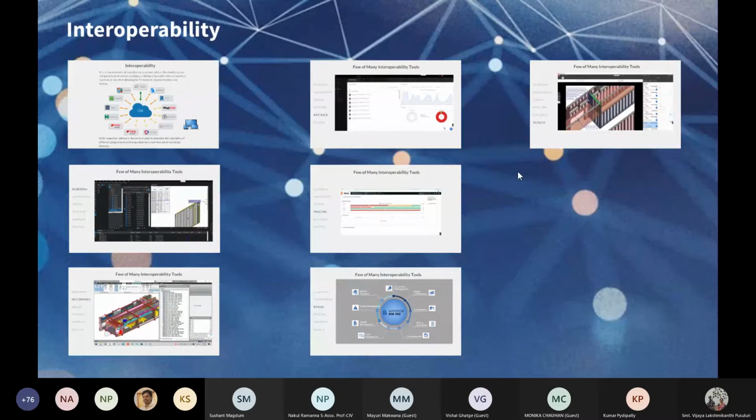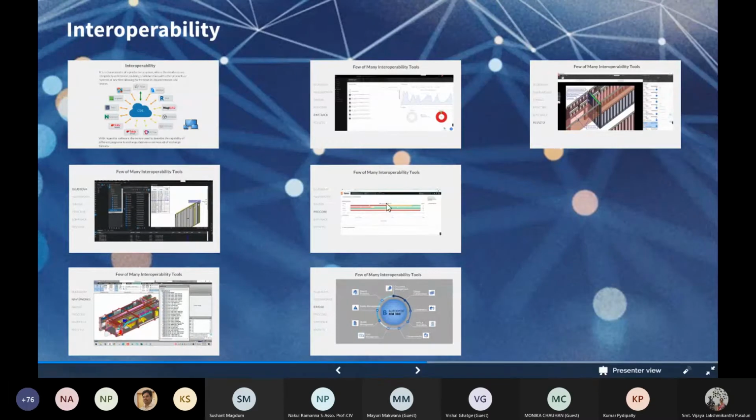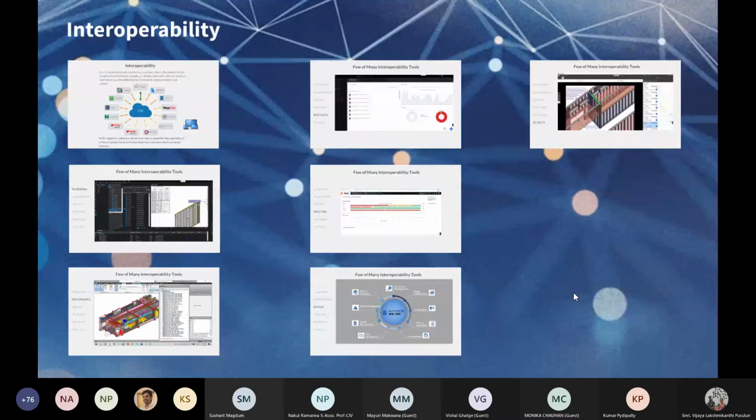So there is a total difference between Navisworks and these tools. With Navisworks, you need Navisworks Manage or Freedom, depending on the version or the functionality you're going to use. If you're doing clash detection, you need Navisworks Manage. But apart from having the software, you need each and every stakeholder's file combined together, and that's when you can do clashes.